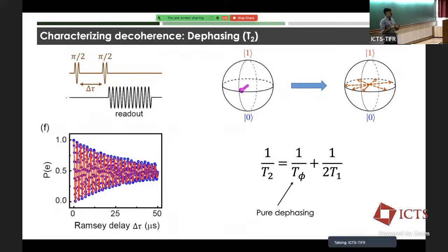And if you want to look at how the qubit frequency is fluctuating in time, then you can't do that with the full curve. But you can sit at one point, and if you have a very high fidelity measurement, you can get some information. But it's a trade-off, right? It's basically the trade-off of, do you integrate long enough to increase the signal to noise ratio, or do you keep the time window small so that you have more resolution in your measurements?